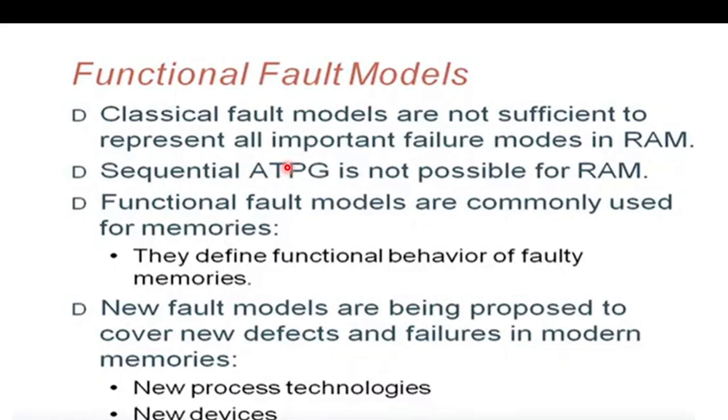Can we consider all of the memory cells as flip-flops and use sequential ATPG? That is also not possible when the memory is huge. And new fault models, which become hugely complex, are being proposed to cover new defects and failures in modern memories, new process technologies, and new devices.